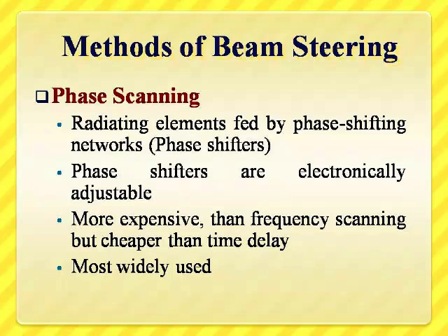So let us summarize what are the advantages we are going to derive by this electronic scanning method, or simply ESR, electronic scanning radar system. As we are going for electronic means, the scanning is done at very high speed. You can have multiple functions by the same radar system simultaneously. One beam can be used for search operation, another beam can be used for tracking operation. That means you can have track while scan done very easily with a phased array radar like this.